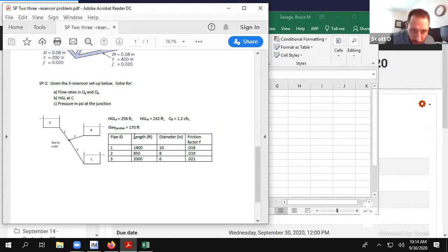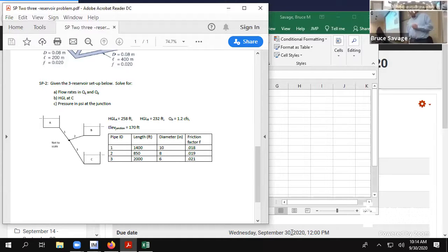If I can just interject there for a second, sorry. Where you can calculate the C value for it and you know what the Q value is, C times Q squared will give you what the head loss is through that drop, right? Correct. So if you calculate that and you know what the head loss for the HGL is for that section, you can automatically tell that the HGL must be lower than the other ones because of the value that returns.